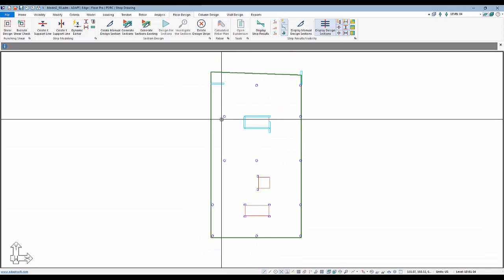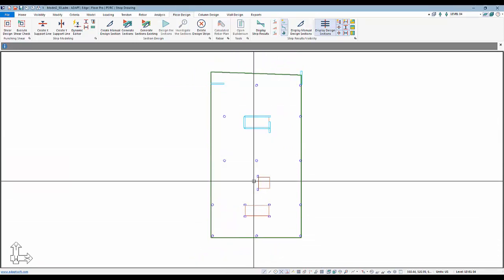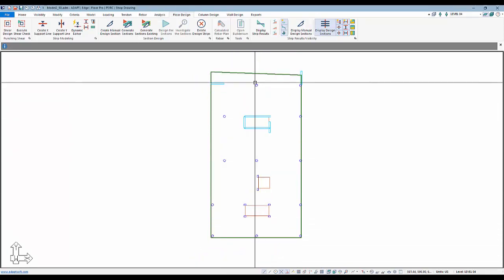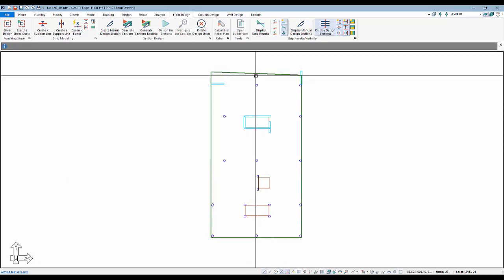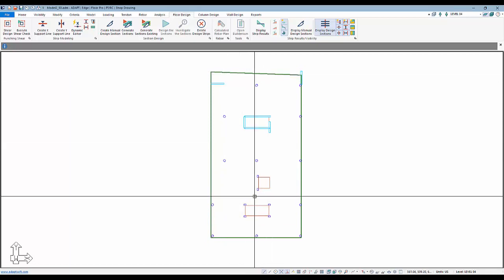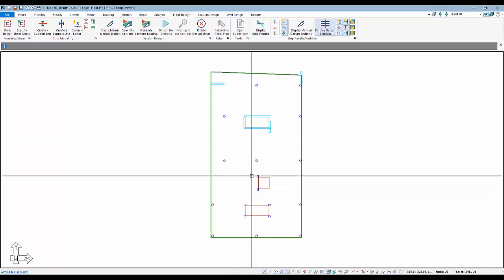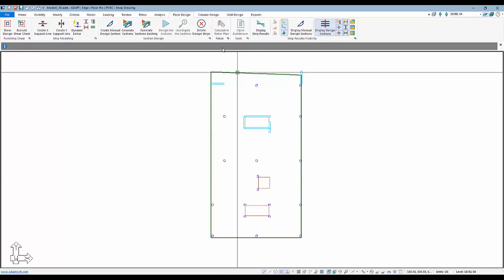It has a few interesting things about it, particularly the column layout. So before we start defining the strips, we need to determine how the tendons are going to be laid out schematically for this type of slab. We're going to start by selecting the slab.